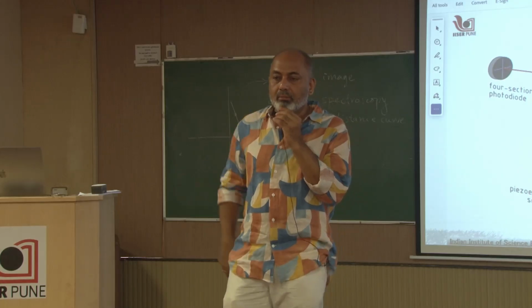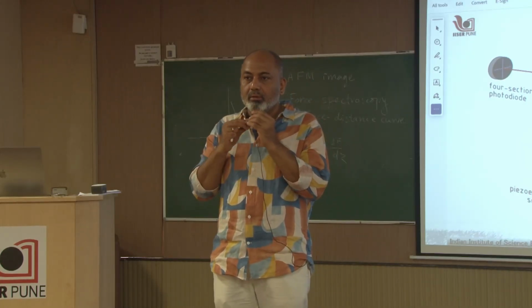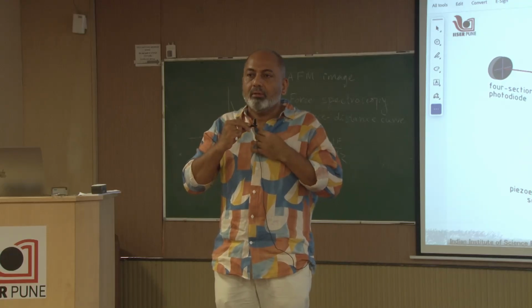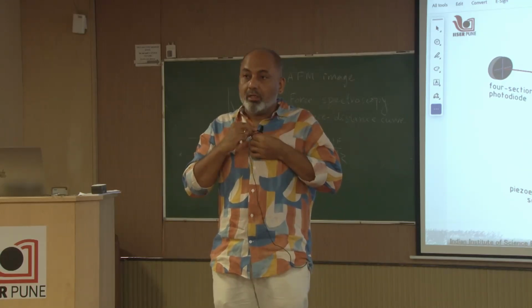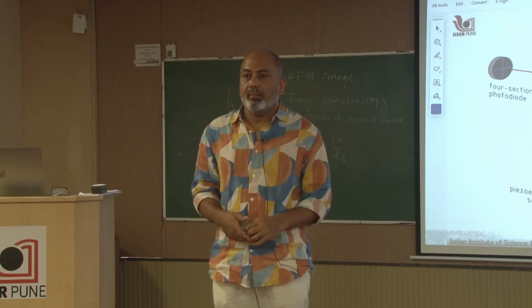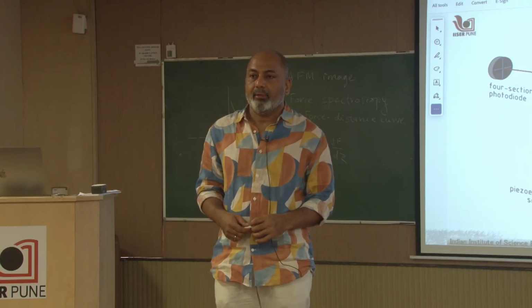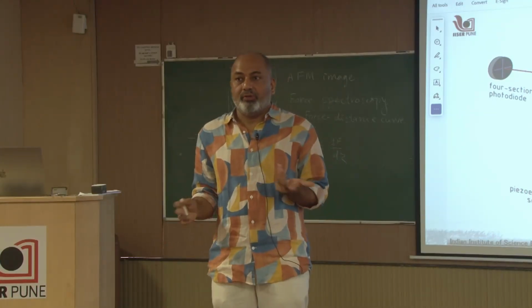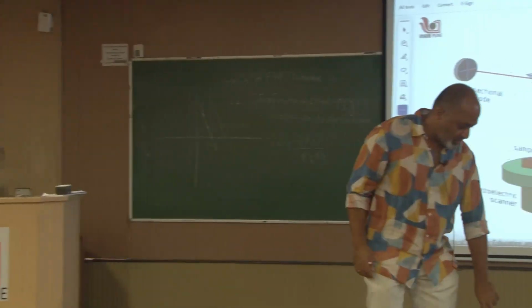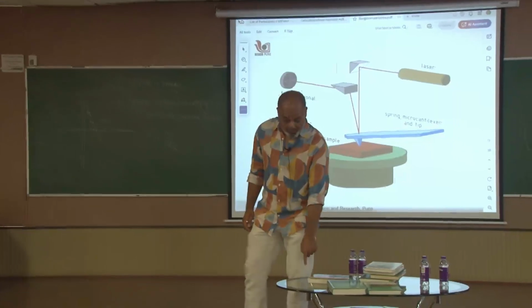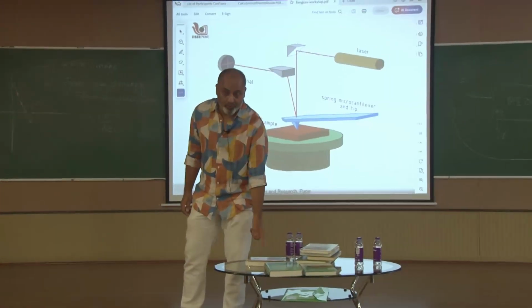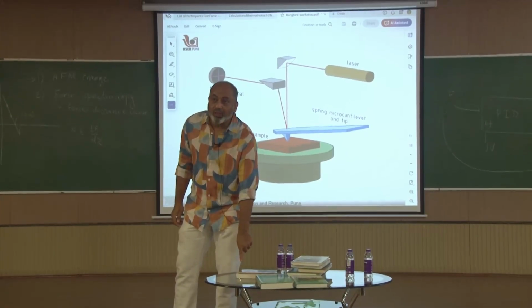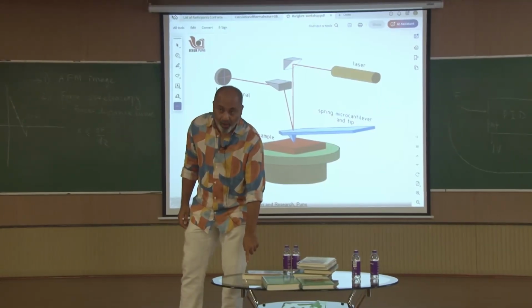Whatever my electronics are, I'm going to get a signal, whatever the topography, because the topography is not revealed. So how do I understand what is noise and what actually is signal from PID scanning? PID may respond slower, while going on the edge. The edge is sharp, so it's quickly changing from 1 volt to 1.2, as we said. So the sharp edge will not reveal itself as sharp. How do you tackle this?